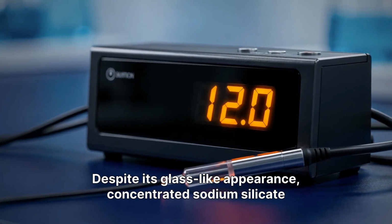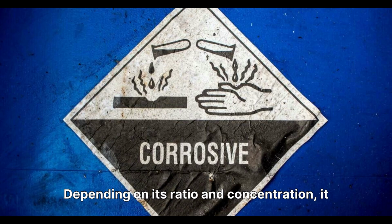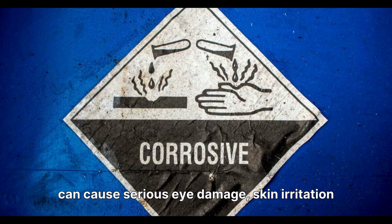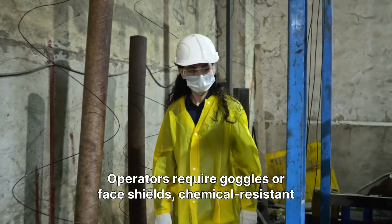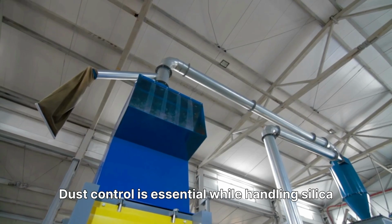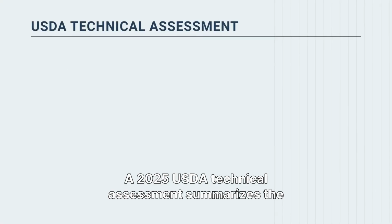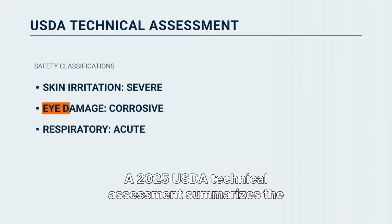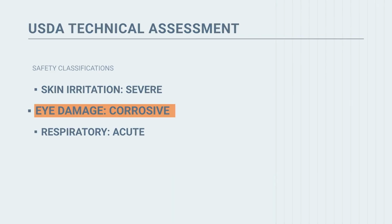Despite its glass-like appearance, concentrated sodium silicate is strongly alkaline. Depending on its ratio and concentration, it can cause serious eye damage, skin irritation, or chemical burns. Operators require goggles or face shields, chemical-resistant gloves, protective clothing, and controlled spraying. Dust control is essential while handling silica sand and powdered products. A 2025 USDA technical assessment summarizes the concentration-dependent skin, eye, and respiratory hazards.